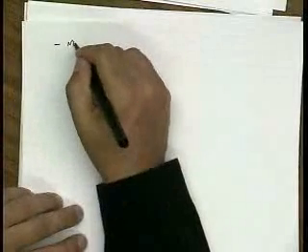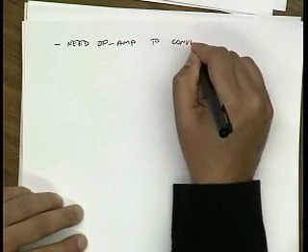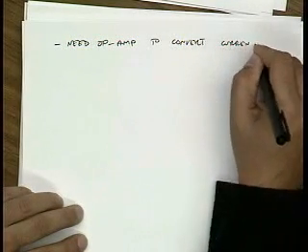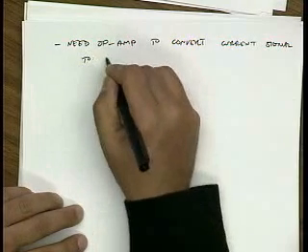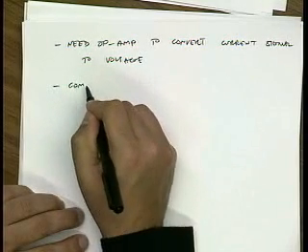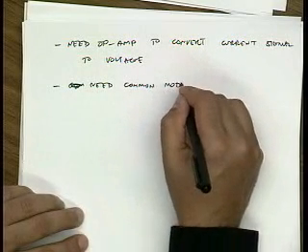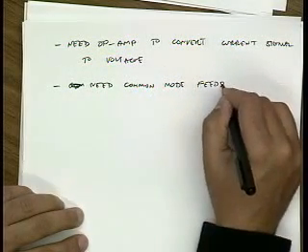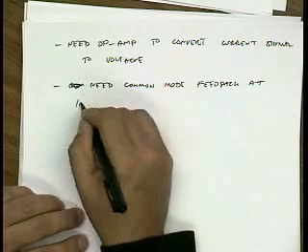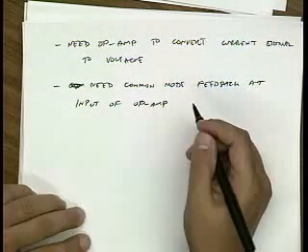There are some disadvantages. One of the big disadvantages, we need this op-amp to convert current signal to voltage. And you also need common mode feedback, because it's a fully differential op-amp.